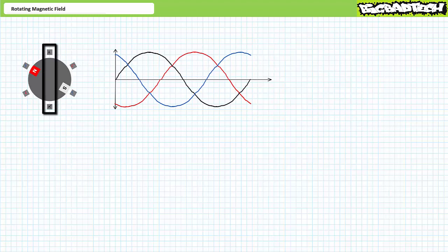Winding A remains energized by phase L1 in black. L2 and L3, however, swap seats on the bus. Winding B is now energized by phase L3 in blue, and winding C is now energized by phase L2 in red. Let's start this analysis with the rotor in this present position at time t equals 0. Ideally, we should still see the stator establish a rotating magnetic field, only this time in the opposite direction.